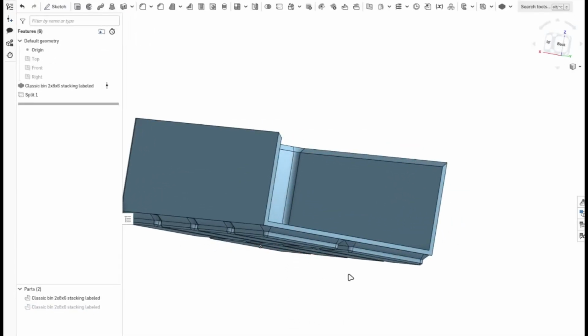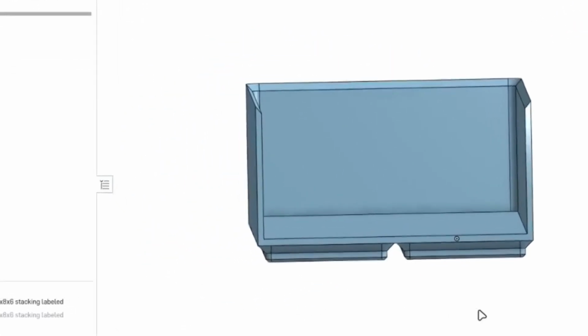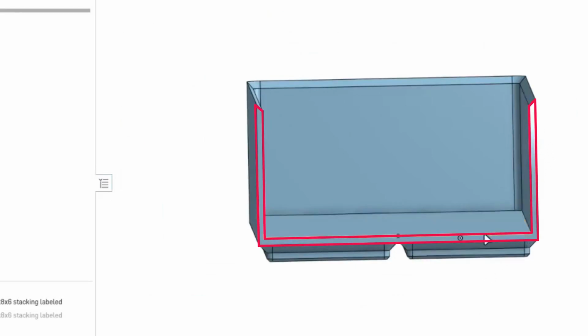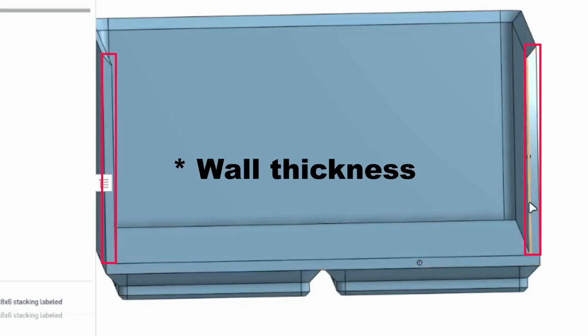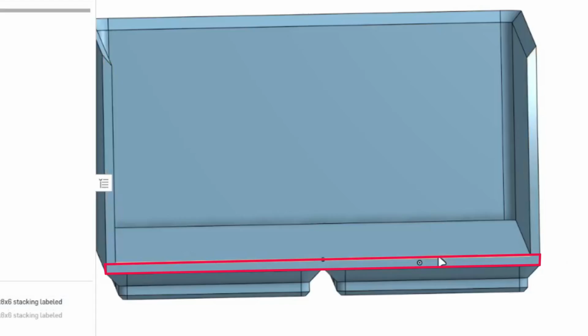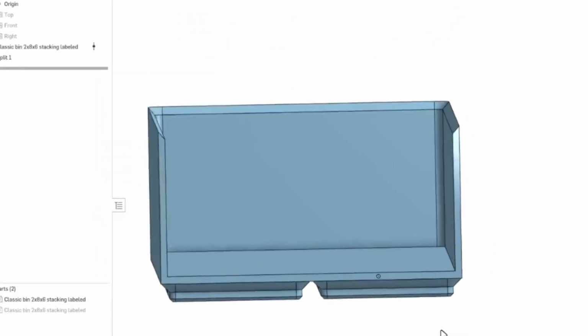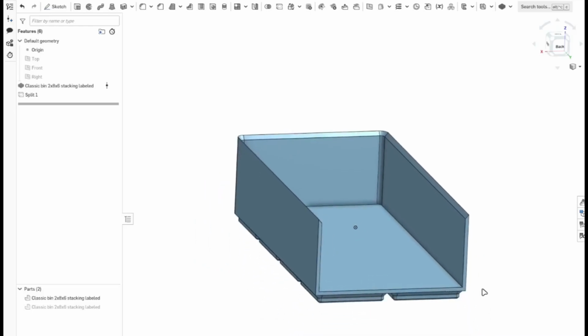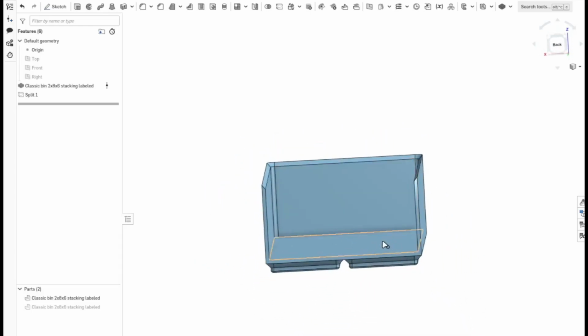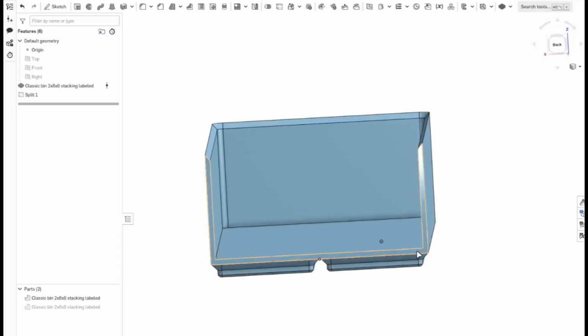Now if you see here, you don't have much contact surface area to glue. This area which you are going to glue is not large enough to glue both the parts together. So the contact area is very small. From here to here is 1.8, and this will be 2 mm, which is not good enough to glue together. If the part is bigger than this, then you'll have a problem. Even for this one, I would not recommend gluing with this small contact surface area.